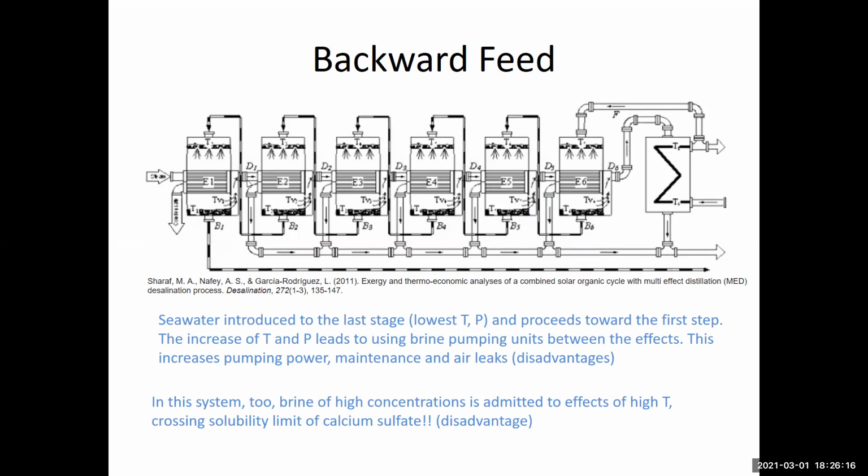And then water will leave, and the vapor that's formed here is going to go to the next effect. So the vapor that you are producing as product, before you take it, you condense it, and while you are condensing it, you are making use of that by generating an additional amount of vapor. So the vapor here is going to move always from left to right.